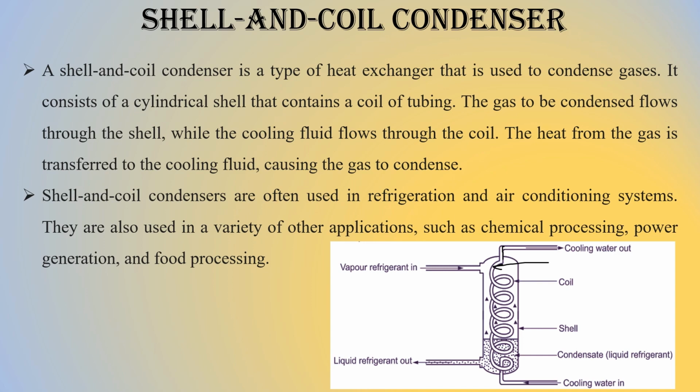Now in the previous slide, we saw that both the refrigerant and the cooling fluid were in tubes, but this time the cooling water is in the coil and the vapor refrigerant is not in any tube. It is in the shell. As the vapor refrigerant moves in, the cooling water simultaneously comes in.